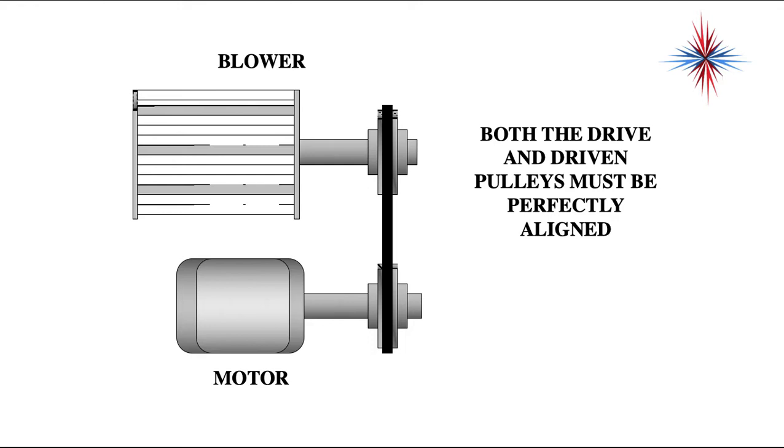It's very important. The drive and the driven pulleys must be perfectly aligned. You can't have any side-to-side movement on this, and they have to be in perfect alignment or the belts will wear out extremely fast.